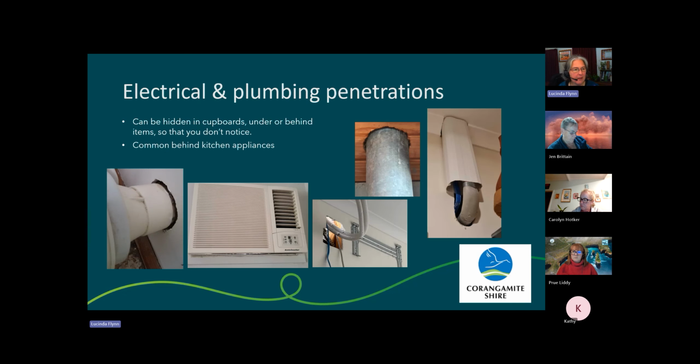Even in a brand new house, these are the types of gaps that you're going to get, which is when things get installed and tradespeople just don't take a great amount of care with filling the hole that they've made. This sort of hole might seem small, but in this situation, that was leading into a ceiling cavity because it was a second floor room, which means there's going to be really hot and dusty air coming through there all the time, and also you're losing air through there.